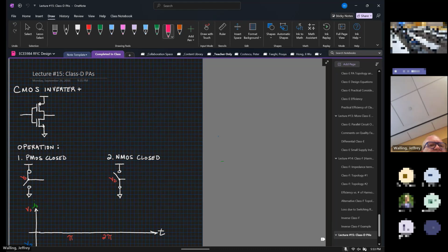So, in general, though, I just want you to take that when you're making a linear power amplifier, linear just means that we're using the device as a transconductor for some portion of the conduction cycle. So we're using the GM of the device. And when we're looking at switching amplifiers, we're just turning the device on and off and pulse shaping. And those are the fundamental basics of the power amplifiers.